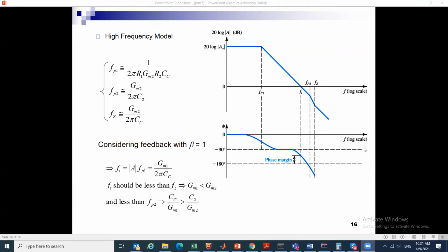Great. So this concludes stability, it concludes the analog design, and this is the most complex thing: pole shifting, new pole, and the relation of the intersection of 20 log A with the feedback loop. Now we're going to move to part 8.